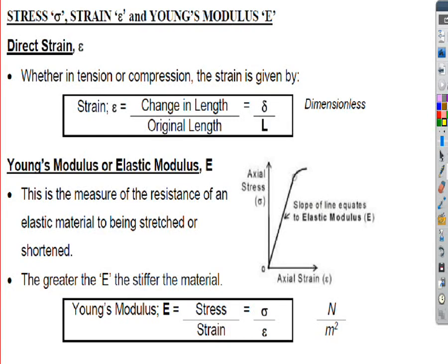Okay then, last week we looked at the basic formula for direct stress, sometimes called axial stress, and that was force over area. I'll show it again to you in a minute, but just for your reference, the direct stress, and I normally use the Greek symbols, is that sideways 6 looking symbol, which is lowercase sigma, equal to force over area. And we spent quite a bit of time looking at that formula, rearranging the formula and that kind of thing.